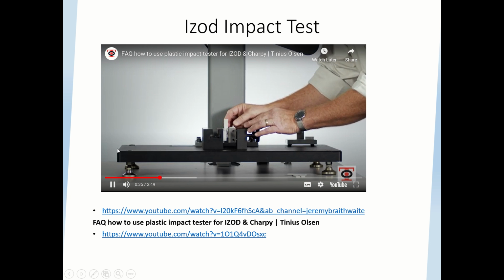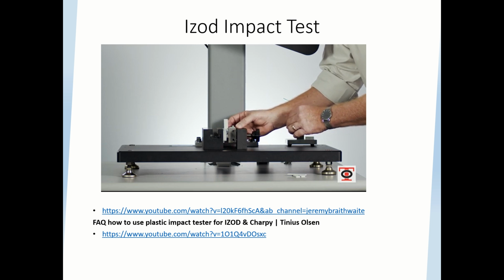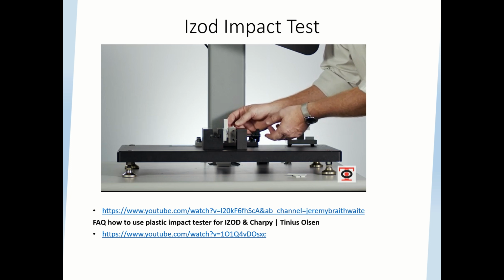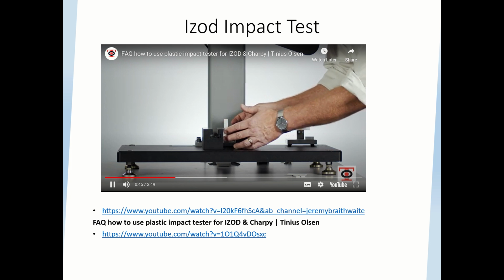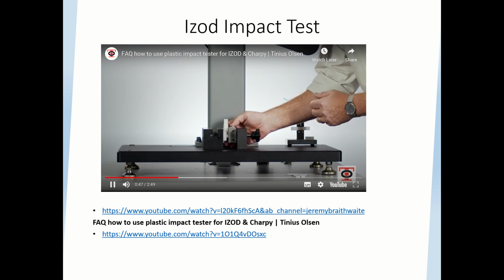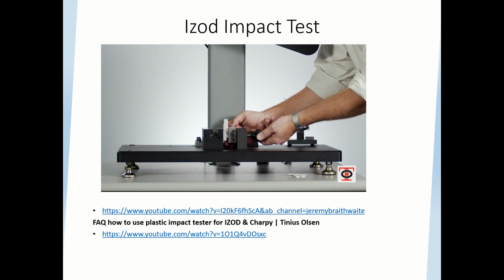Gauge building to the top of the vise. This helps you simply place the specimen in the proper position, and you can do that consistently. After you have it in position, we also have a stop in here. Again, that just makes sure that you're placing the specimen in the same position each time. And then you can clamp the specimen in position simply by turning the knob.